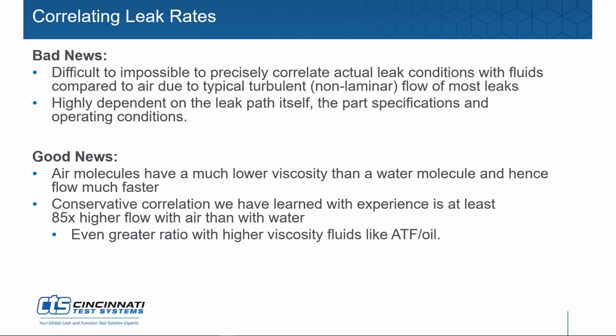Yep, exactly. So like you're saying, correlating flow rates, the bad news is it's really difficult to precisely correlate flow rate because of those characteristics that are changing. The good news is when we're using leak test technologies, we're using air molecules, whether it's pressure technologies or trace gas technologies, and those gases have much lower viscosity, so they flow more readily through a hole size. If we start doing some calculations and estimations, you will find that air will flow through a hole size 85 times more quickly than a liquid like water or oils.